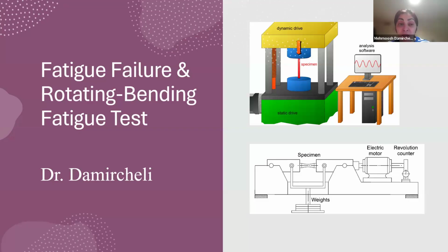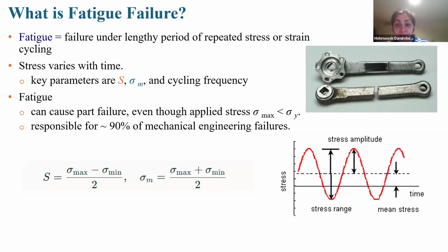So fatigue is very important, because we expect failure to start when stress reaches sigma UT, or ultimate tensile stress, but under these loading conditions it will occur at a sigma less than that, or maybe even less than the yield stress.